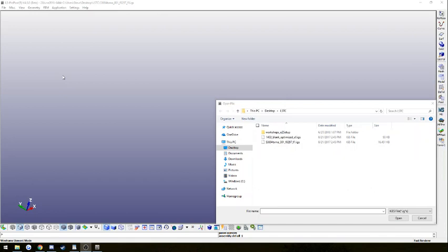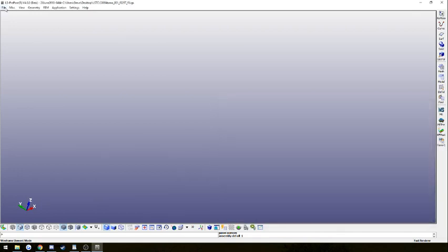If you followed the steps in the first video, you should have a training folder consisting of several files. In this folder, I've extracted the only 2 files that will be necessary for this training exercise, the blank IGES file and the tooling surfaces, including the punch, die, and binder. Now that we have these files, let's go into Prepost and see what we can do.